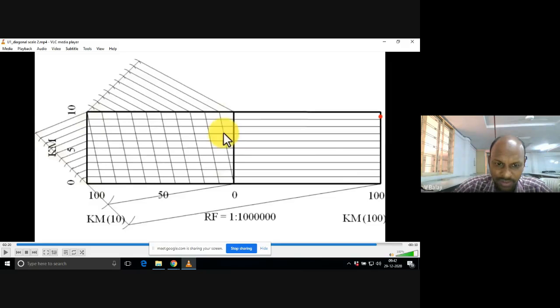And you don't do anything with the diagonal scale. If you take 20 parts, you need not do anything with the vertical height. So what is the use of this diagonal scale then? Such questions will come. Understood? If you divide 20 parts, each part on the right hand side is 10-10, left hand side also 10-10.